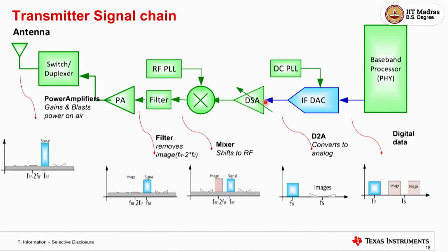Like suppose you are talking to someone very close, right? The standard allows that this signal will be attenuated, so you don't blast too much. You would have seen in your Wi-Fi, right? You can actually change the power level of your Wi-Fi. If you have a room which is like 3 blocks away, you will have to blast power. You will see some dBm, like minus 40 dBm. Or you can go to minus 60, then your radiation will be lesser if you go to lower power because you are around your Wi-Fi. It's a similar concept. So this digital step attenuator only does the change of what power level you want to do.